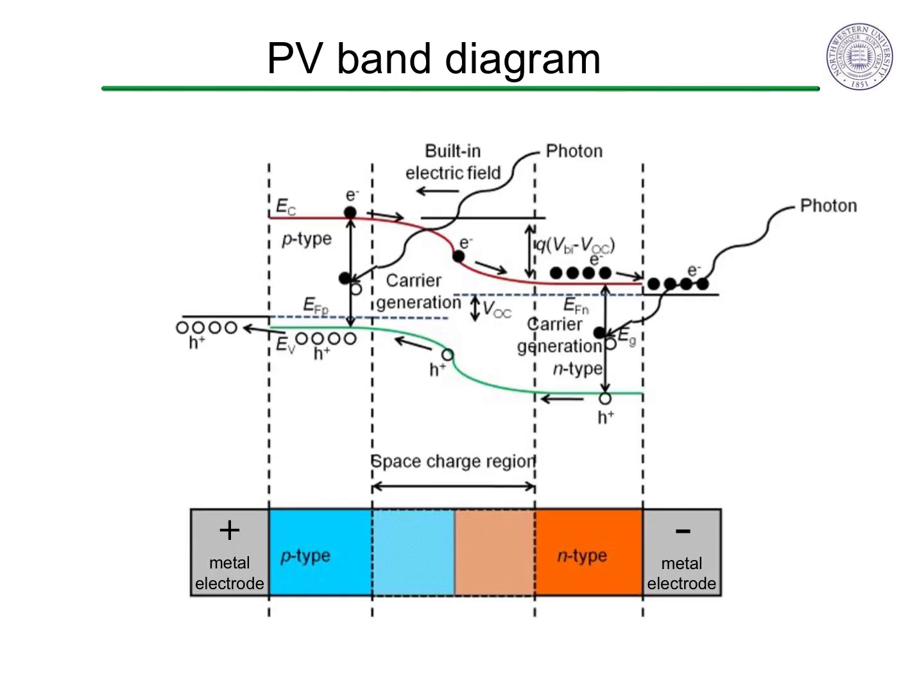In summary, a photovoltaic generally has a heterostructure that can separate photoexcited electrons and holes. The photoactive region is a semiconductor or insulator that absorbs photons and makes electron-hole pairs with long enough lifetime to make it to the desired electrode before non-radiative recombination happens. The electron-hole separation can happen by drift because of the heterostructure producing a built-in electric field, or by selective electrodes which allow only one kind of charge carrier to diffuse in while reflecting the other type. The built-in voltage can be created by an NP junction like a silicon solar cell or a metal insulator junction. The usable thickness of the active region will be determined by the minority carrier lifetime and mobility.